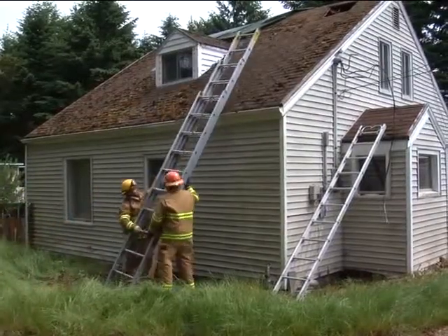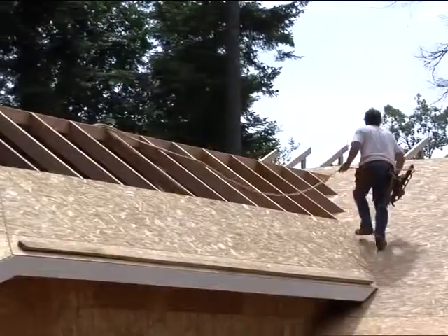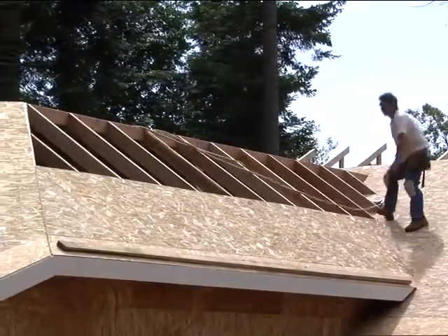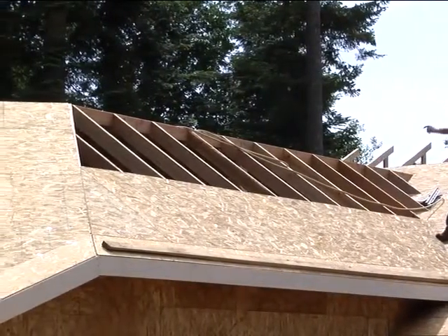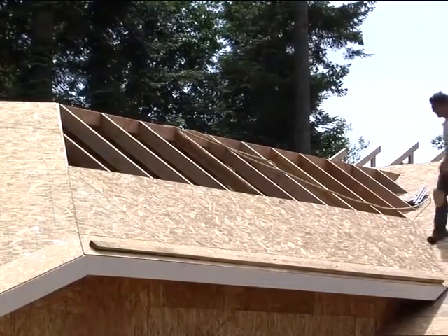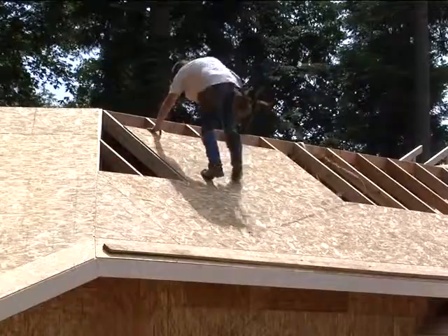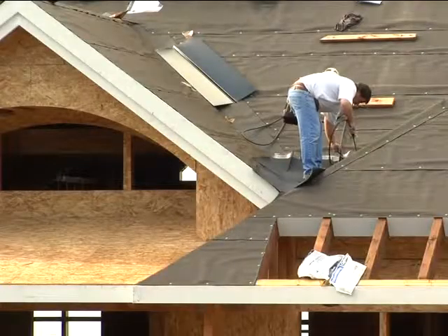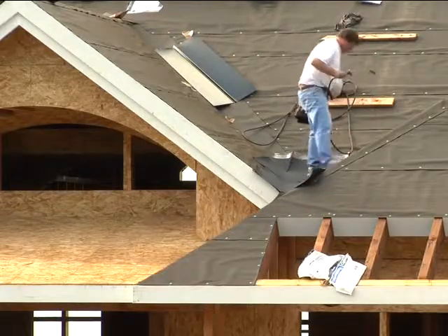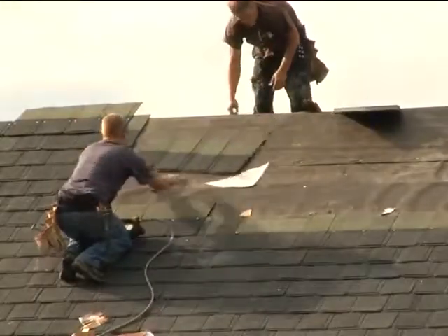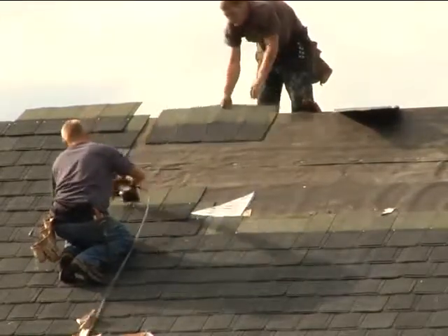A pitched roof is elevated in the center and slopes down to the edges. Pitched roofs on houses are usually made from wood rafters or metal trusses that are installed directly from the ridge to the wall plate on top of the outer walls. Sheathing materials are applied over the entire roof. Pitched roofs usually have a covering of roofing felt applied before the shingles are laid. Shingles can be made of all types of materials, including wood, metal, slate, tile, or composite materials.